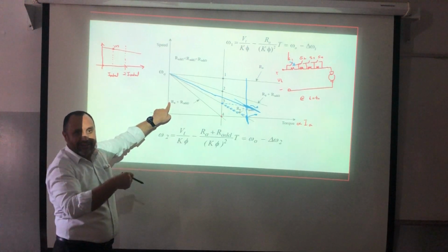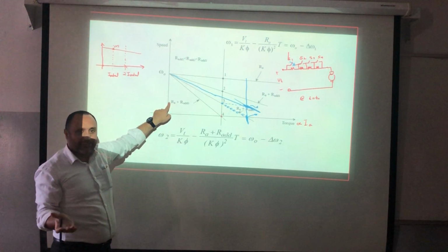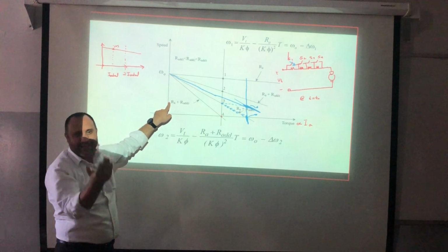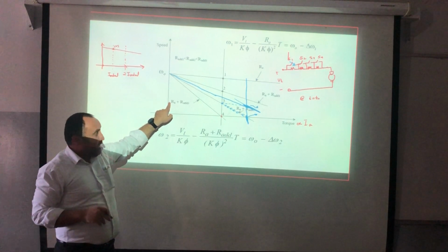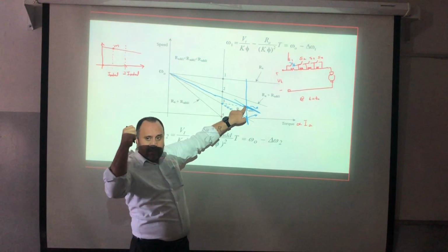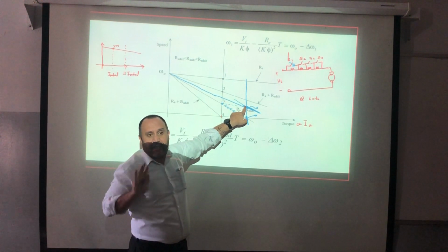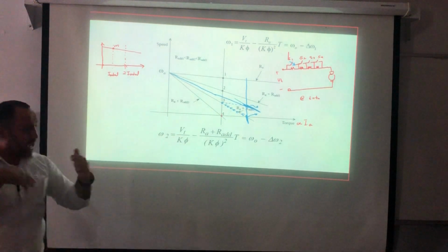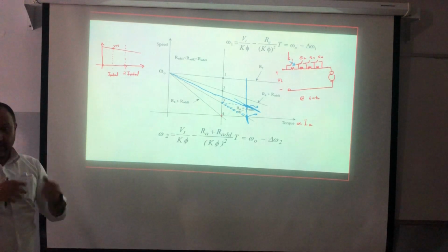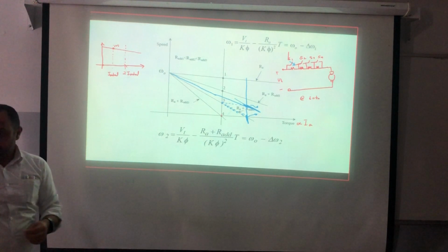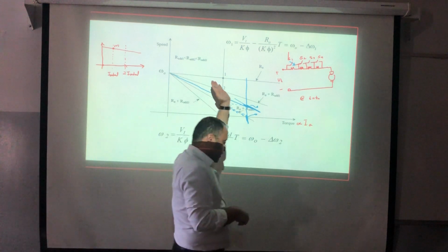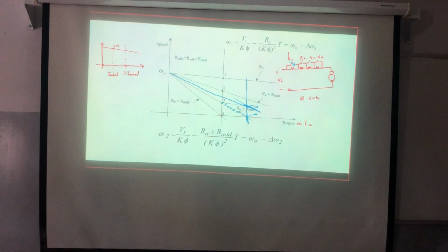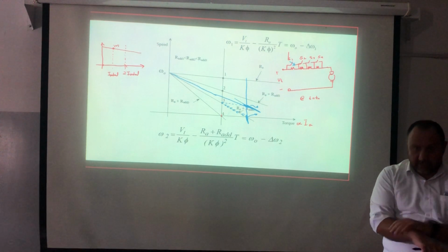Of course you have delta omega. But simply, I need omega. Because if you have delta omega, you should subtract from omega to get what? Omega. Now at this point, what am I having? I'm having the current, I'm having the voltage, I need EA. From where? From the previous point. Good? So now I can calculate the needed resistance to be adjusted in order to go from 0 to the rated speed without increasing the current more than twice, for example. You are getting the point? Good.